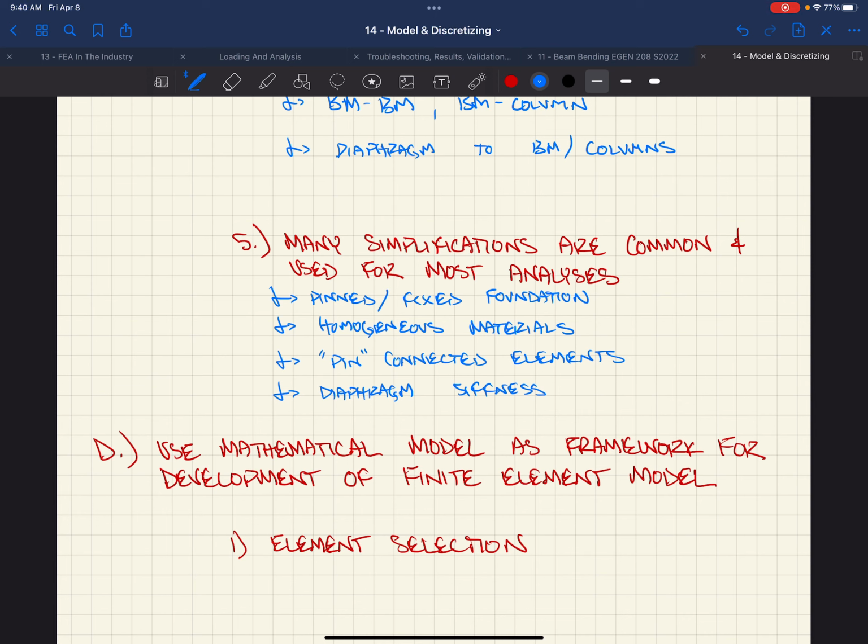If you assume that it's a continuous beam that runs across this, which is the way I would typically do it, especially if you have multiple spans, I just go in VA and draw a member. All that member is just the same member across the entire thing. Maybe you've got 7 or 8 of these bays, right? Based on that, you get 1.25 WL. You get 0.375. With all the shear walls being the same stiffness, you're saying? Doesn't matter.